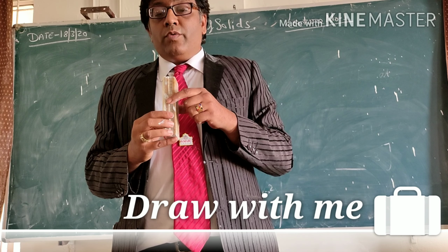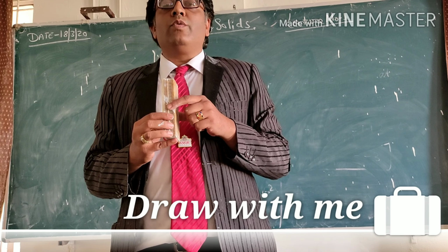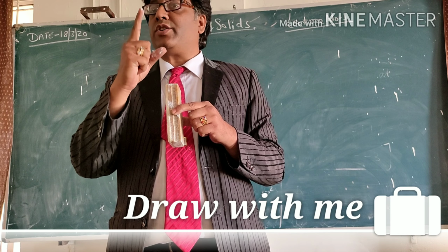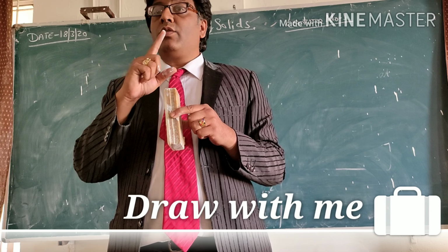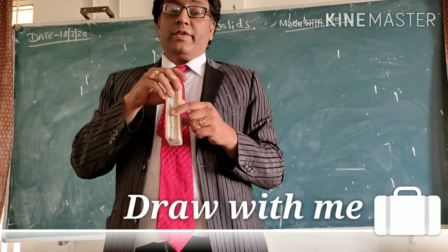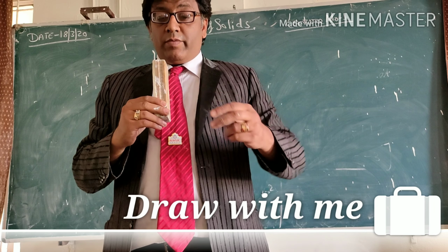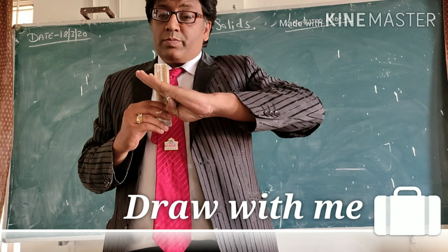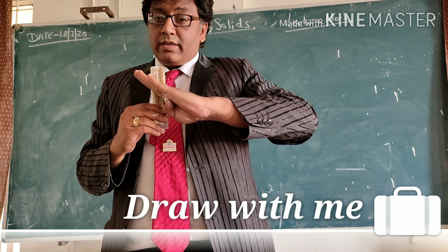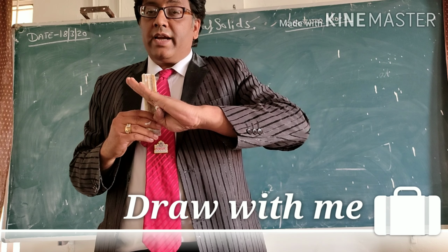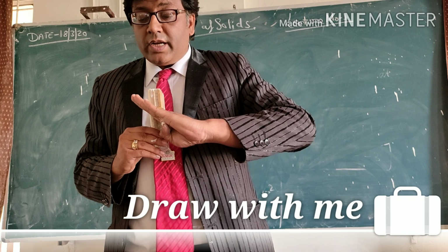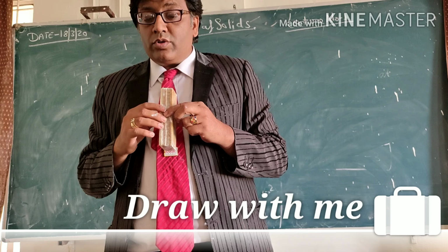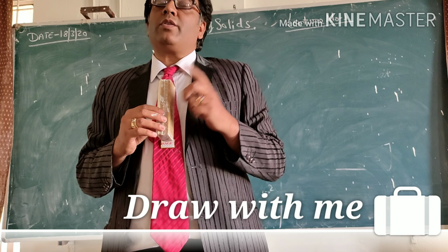The top view which we see is not the true shape of the sectional plane. Because it is cut by this particular plane, which is already inclined, when we see it in the top view we are not able to see the true shape of the sectional plane.